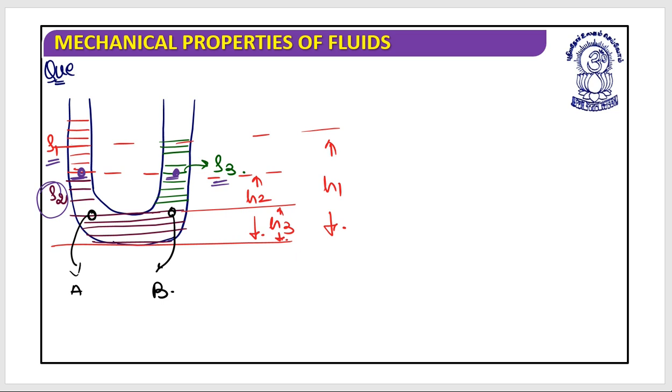So it is not like that, because this equilibrium condition has been achieved due to rho 1, rho 2, and rho 3. All three make this system be in an equilibrium state. I hope this is clear. They are on the same horizontal level, yes. Should we use them? I should say no. We need to always choose a point for which we can have relations for everyone. So this is the point to choose, and that is what we call PA equals PB.